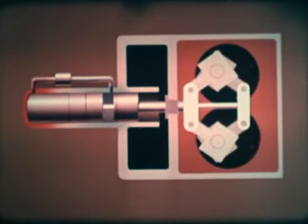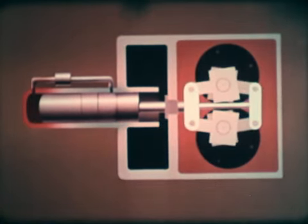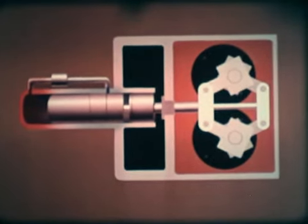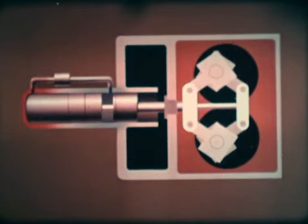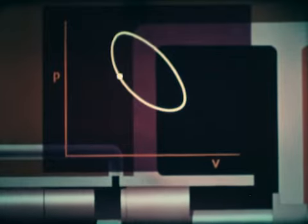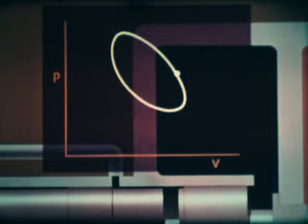These are the four phases of the cycle. First, the gas is driven to the hot space, where it is expanded, driven back to the cold space, and ultimately compressed. With the use of the rhombic drive, the four phases of the PV diagram will partly overlap, resulting in this shape. The work done is still proportional to the area enclosed.